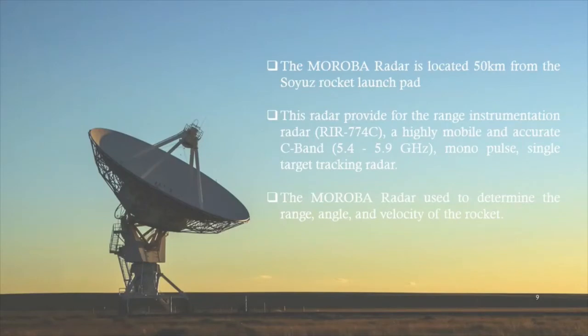Then, about the Moroba radar system. The Moroba radar is located 50 km from the Soyuz rocket launch pad. This radar provides the Range Instrumentation Radar RIR 774C, a highly mobile and accurate C-band, 5.4 to 5.9 GHz monopulse single target tracking radar. The Moroba radar is used to determine the range, angle and velocity of the rocket.